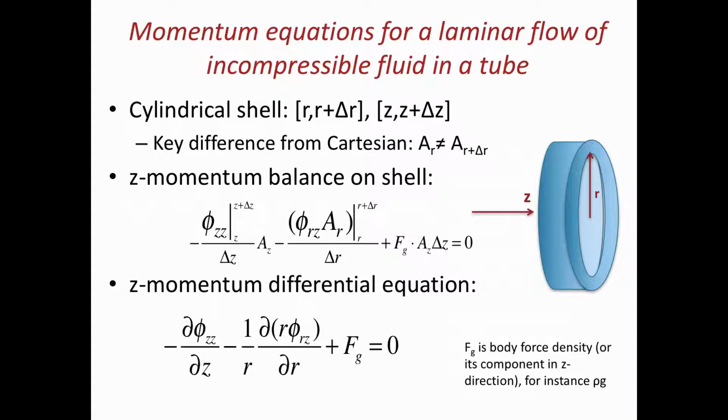Yes, questions? If we have a horizontal flow, don't we have a body force in terms of, so FGR? You do, we ignore it. Because I don't have boundaries that are open in that direction, so it's not going to really flow in that direction. I can't go through if the boundary is closed. So that's a dominant effect for smaller tubes. For larger tubes, it's not. I might still ignore it in order to calculate, but then I have an approximation. My solution is always an approximation, and that approximation works better in some cases than others.